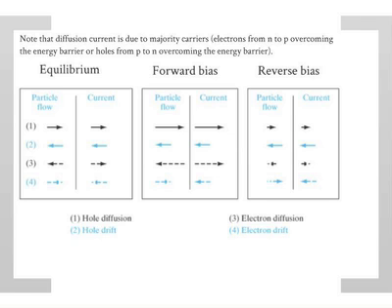And this has to do with the concentration gradient. So you'll end up with lots of holes right at the junction, right after there, and very few holes far away, so they will diffuse. But as they diffuse, they will recombine as well. And that's the current, right? That diffusion is the current. The diffusion of the minority carriers, which actually came from the other side.